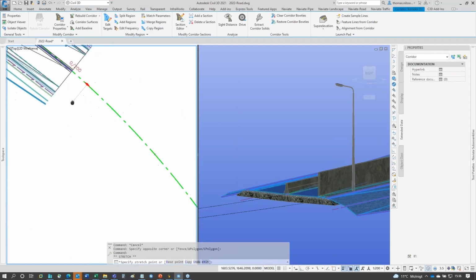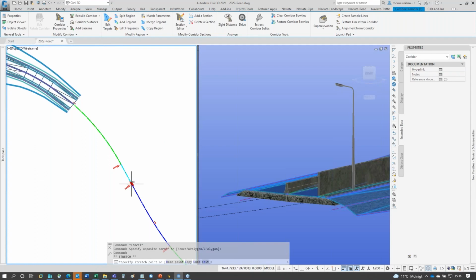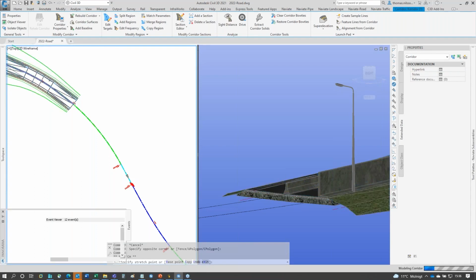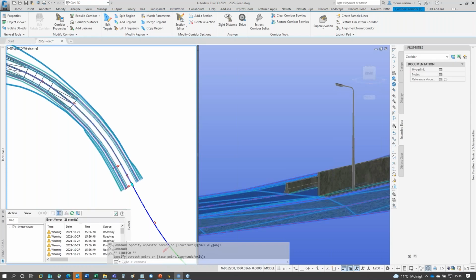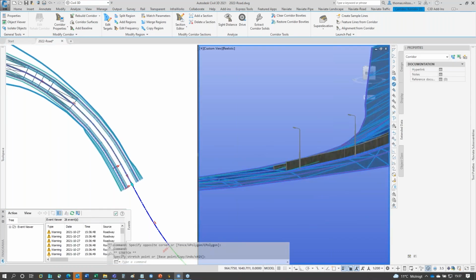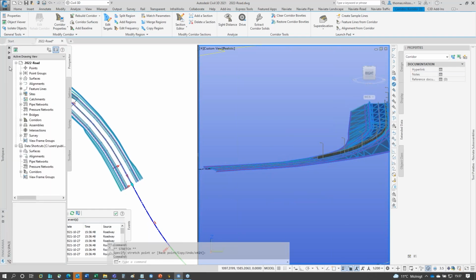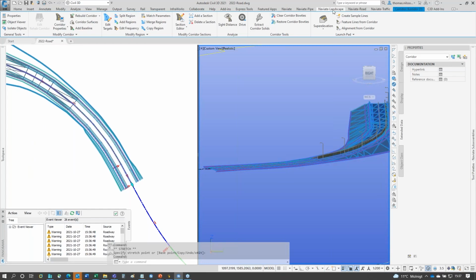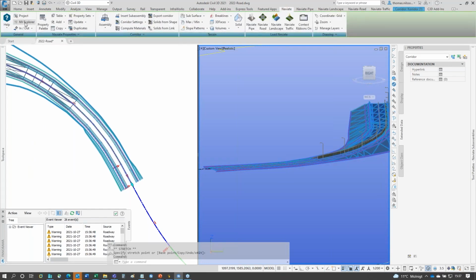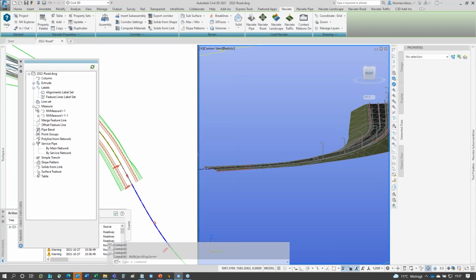I mentioned the update. So let's drag this one a bit there and let the corridor recalculate. We are going to see that the corridor extended, the lines extended. If you use our Naviate Object Explorer, you will see that the measures are in here. I could have, of course, named them better. So please notice the lights there. I will update all.